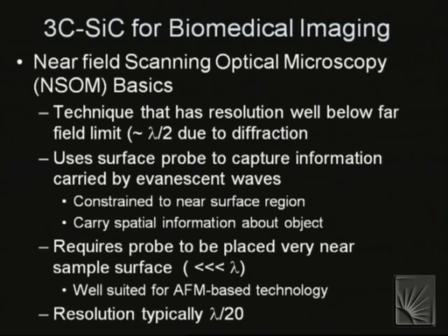So you image the signature of the substrate not by a mechanical deflection, but by the evanescent wave signature that you get from that probe. The attribute one was trying to capitalize on is that these NSOM devices actually cheat nature by having a resolution that's well below the far field diffraction limit.